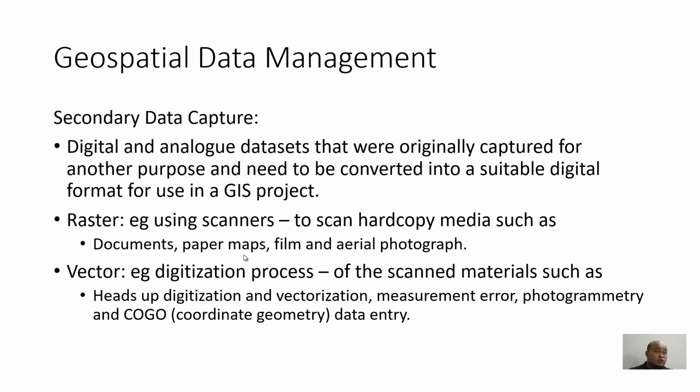It shows the road network, right? But our own GIS project doesn't understand the lines of the road yet. So what we need to do is trace the road and register that particular line as routes. Okay, so that is what we call digitization.